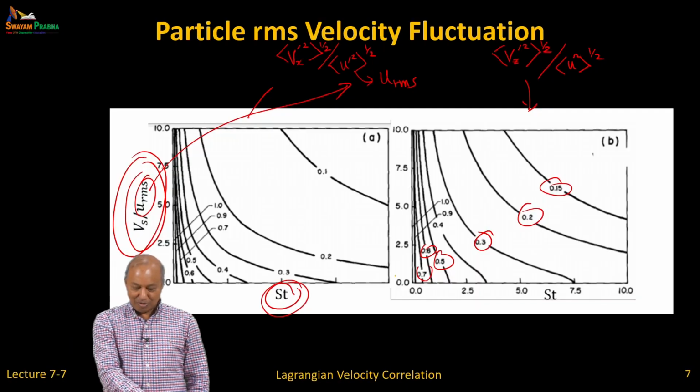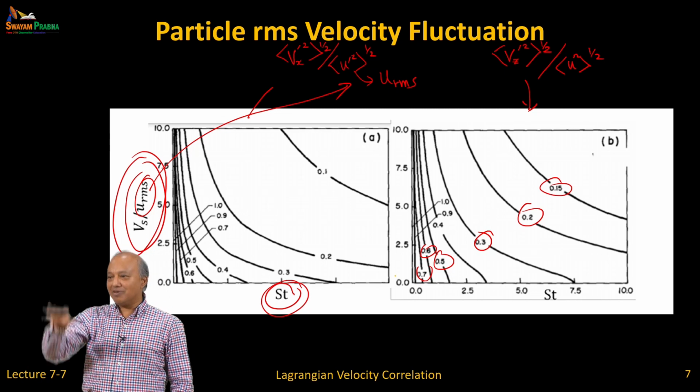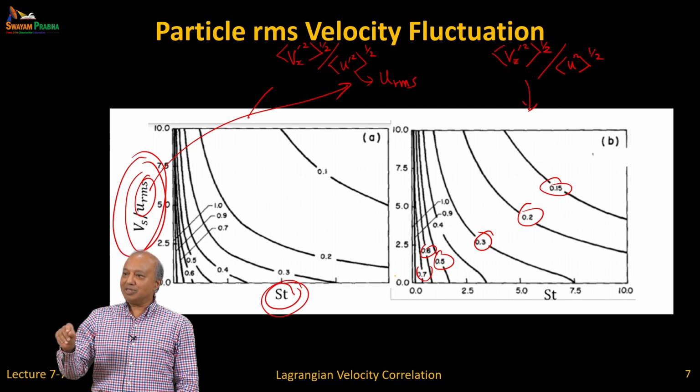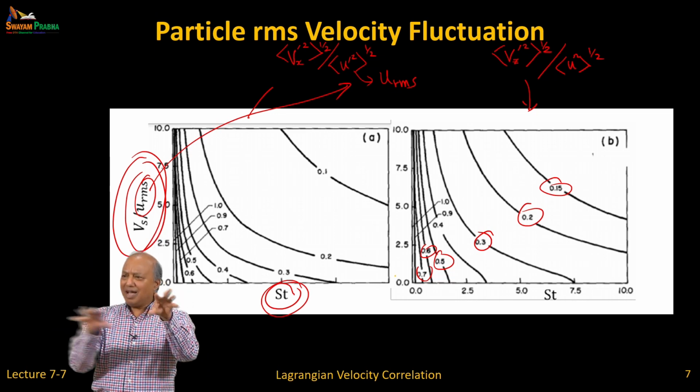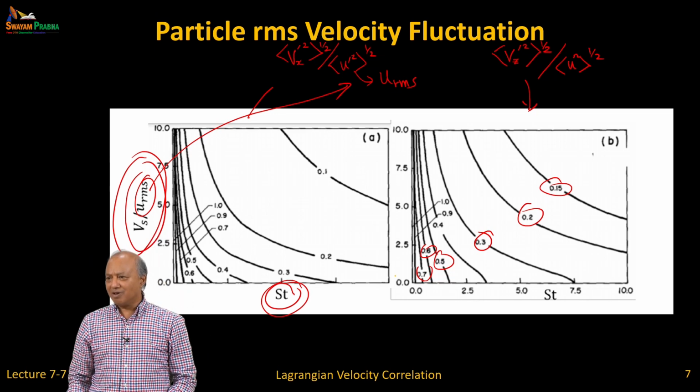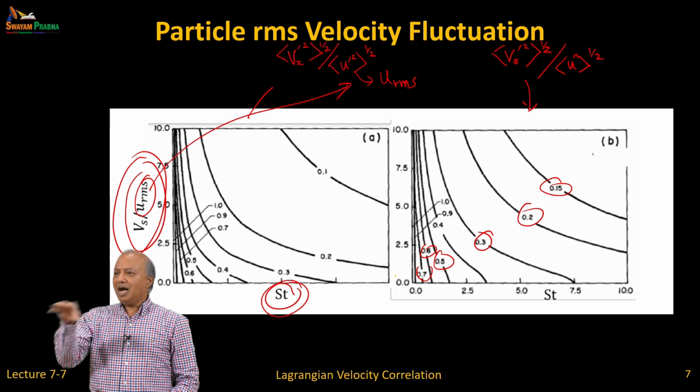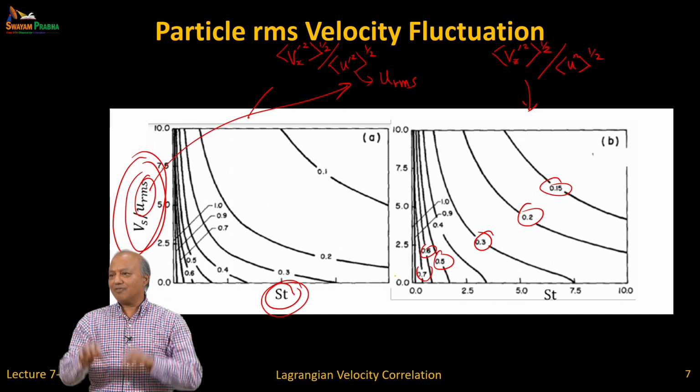What do you mean? Particle velocity? You have mentioned that it's lower than the fluid velocity. Yeah. It's the fluctuating component. That's why I put a prime here. So the mean velocity has been subtracted. So in other words, when you look at particles, they're all falling down, but they're all also having deviation from the falling velocity. So we're asking how much the particle velocity is fluctuating.